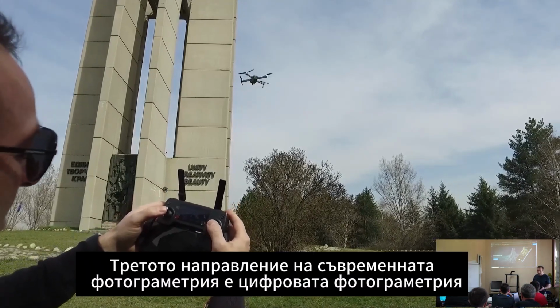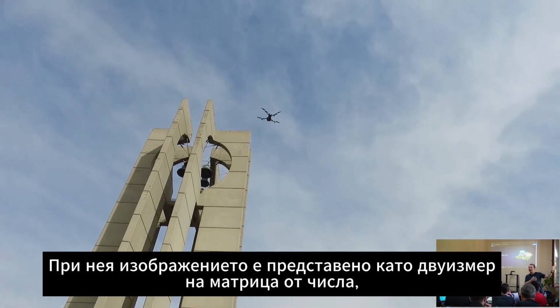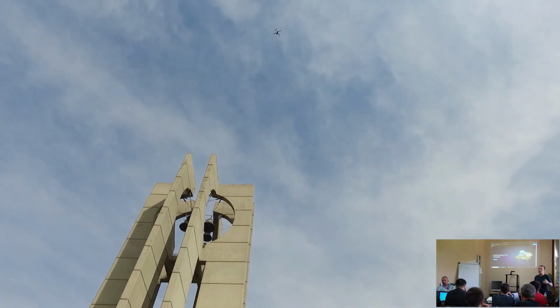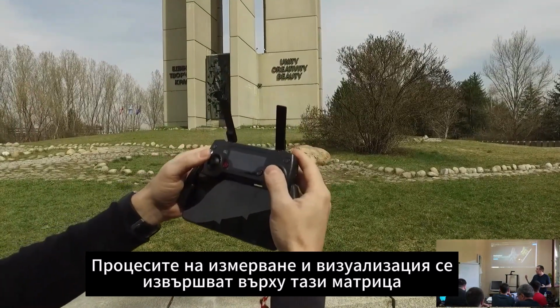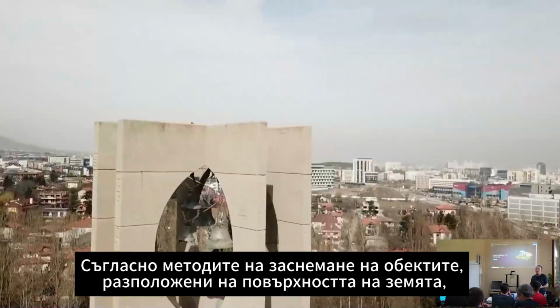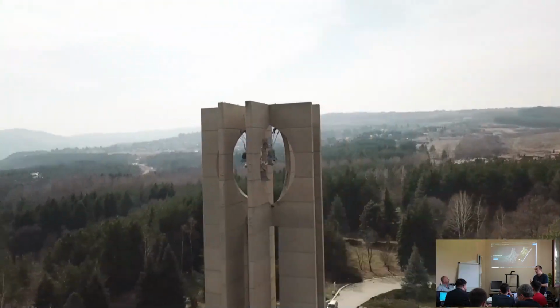The third direction of modern photogrammetry is digital photogrammetry. In it, the image is represented as a two-dimensional matrix of numbers, which is called a raster or digital image. Measurement and visualization processes are performed on this matrix. According to the methods of capturing objects located on the Earth's surface, we distinguish between terrestrial photogrammetry and aerial photogrammetry.